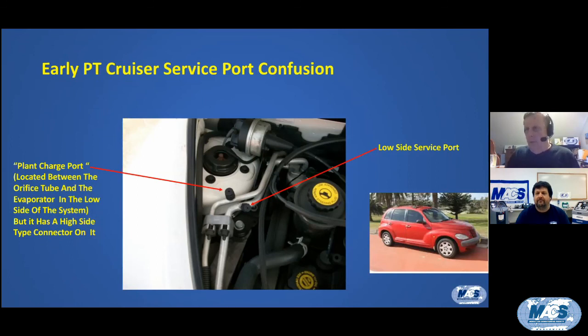But again, we're talking about an inexperienced technician, so he goes ahead and installs another compressor on there. It's doing the same thing. So then they start replacing multiple components. They might replace the condenser. They might replace the lines, the dryer. Sometimes I've run into situations, Steve, where they replace the whole system on the vehicle. And this is a pattern failure.